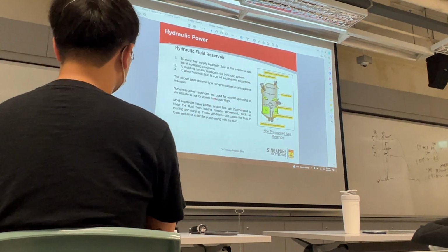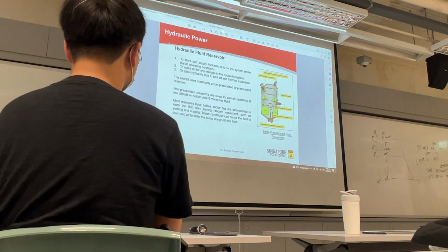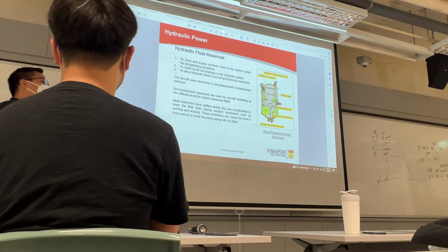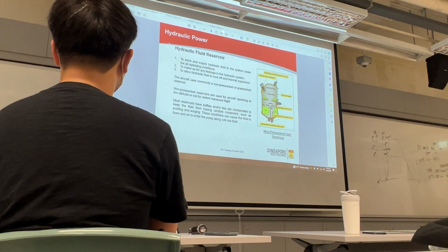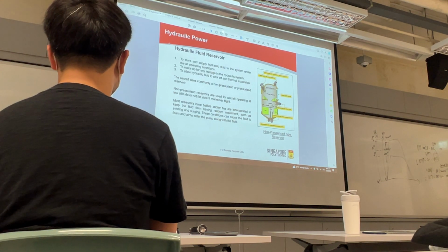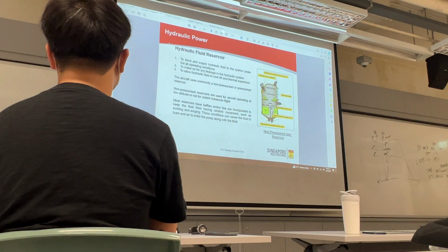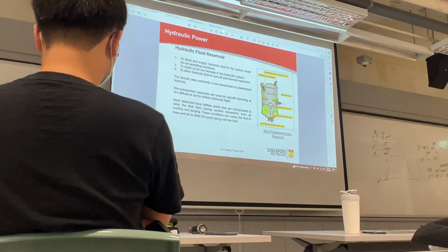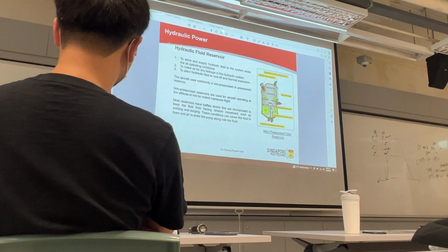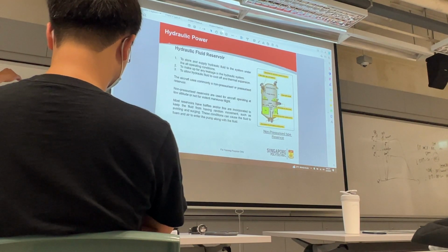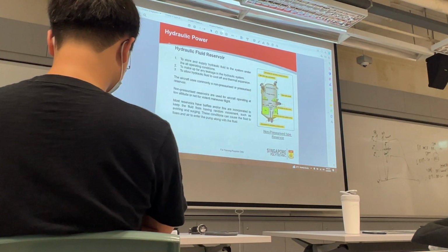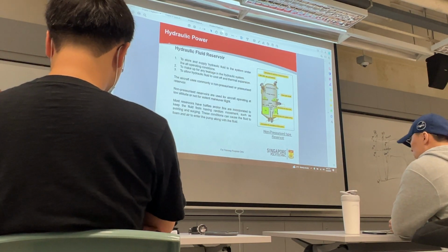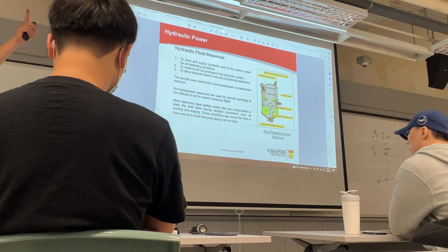Next, the reservoir must take more fluid to anticipate any leakage. For your information, hydraulics has so many pipings in the plane that it is bound to have some leaks. But the leaks are considered acceptable, so the aircraft can survive for the next 17 hours if the flight needs to be that long. When there is a leak, the reservoir level is already there. But if it's quite drastic, you need to go and investigate, and hopefully the color dye is there to show where it leaks from.